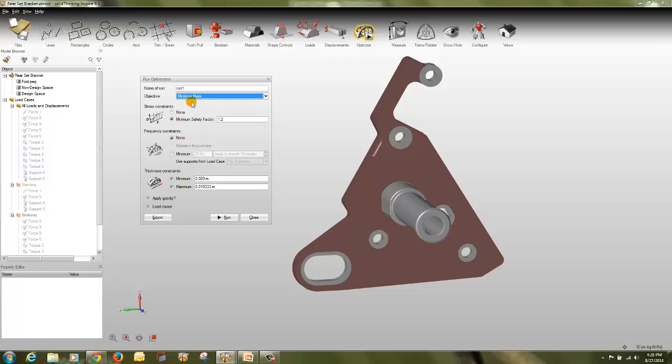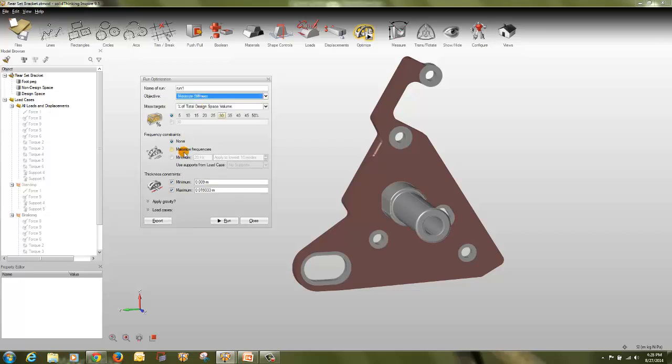So you can have the frequency like maximum frequencies, using the supported load case, so for which load case you want, or minimum frequency, this will be the minimum applied to the lowest 10 modes. This will be the minimum, it should not go beyond this. So when maximizing stiffness, you may choose to either maximize frequency or set a specific minimum frequency.